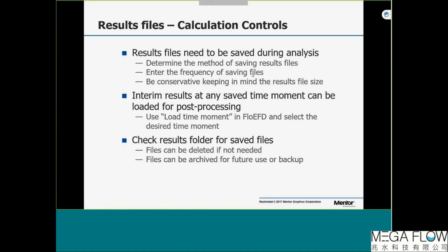Now, in any transient simulation, the more files you save, the more information you have over time, and the smoother results you'll get when you create your animations or look at different time moments. But you have to be careful with that.